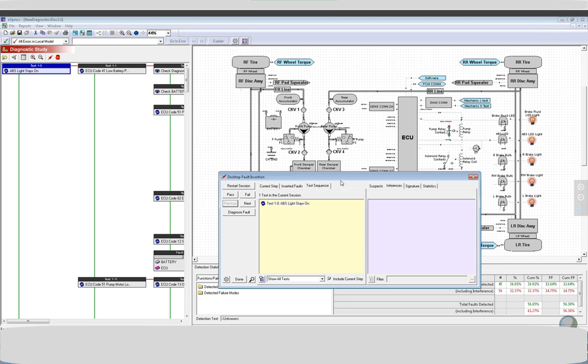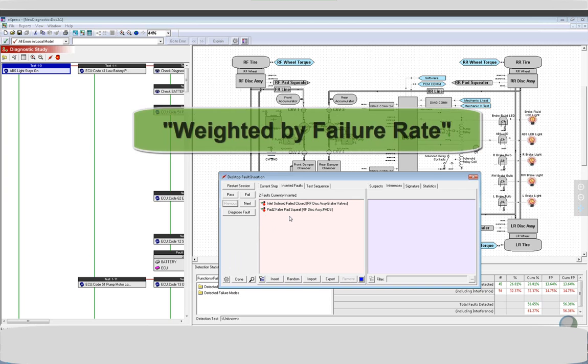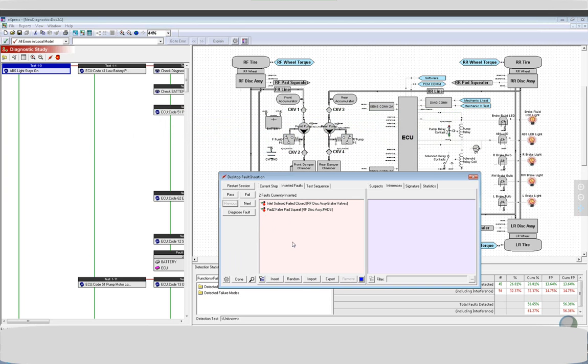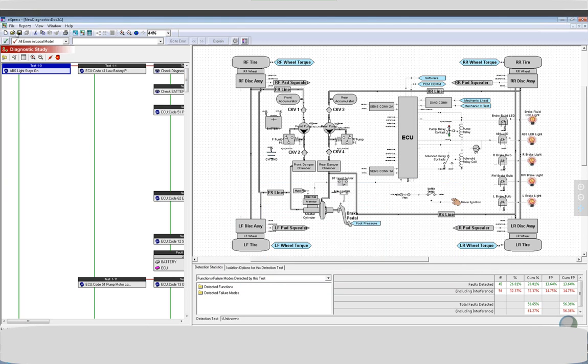Going further, typically part of a diagnostic validation process may be to randomly insert faults but allow the randomness to be weighted by failure rate. Thus, the random selection then drives the demonstration activity. For example, depicting how the bit tests are able to successfully detect and isolate some percentage of those randomly selected faults, and then how that relates to the overall system performance of the implementation of the bit. We can observe the performance of such bit capability either through interactivity with this GUI or under diagnostic validation.